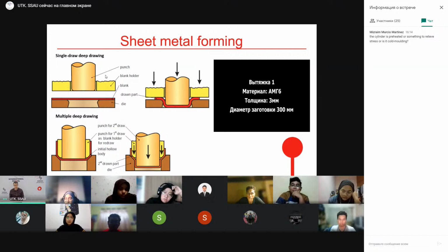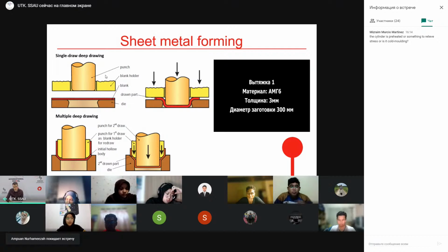In this case, the cost of production tooling is very high and is very important for our technology, because the cost of some dies and punches can exceed thousands of dollars. It's very expensive to produce such parts, because they are produced from expensive tooling material, high-strength steels, and they are produced by machining. So it's very expensive to apply such technology for aircraft and rocket production.